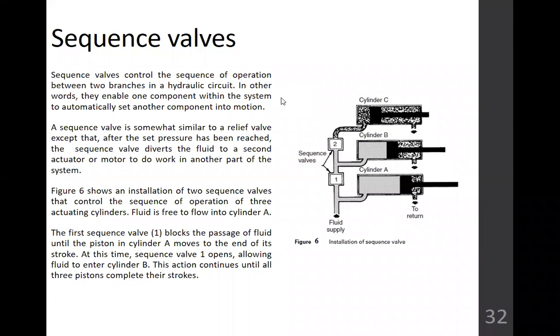Sequence valve. Ito naman. Importante ito pag may sequence. Step 1, step 2, step 3. Sequence valves control the sequence of operation between two branches in a hydraulic circuit. Stage 1, stage 2, stage 3. In other words, they enable one component within the system to automatically set another component into motion.